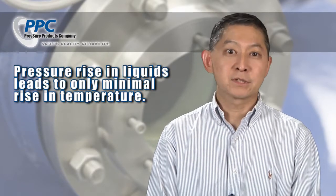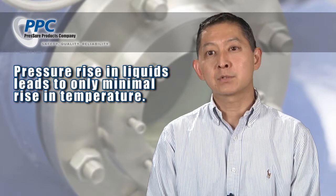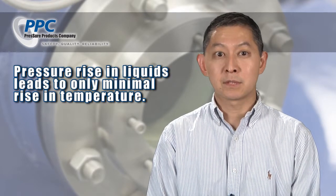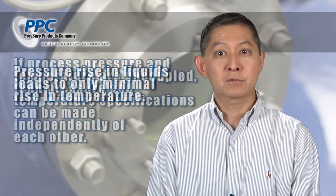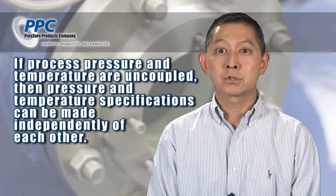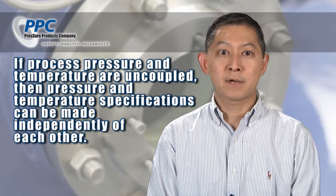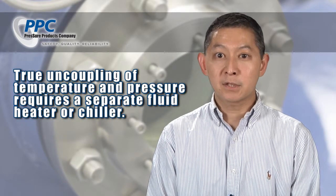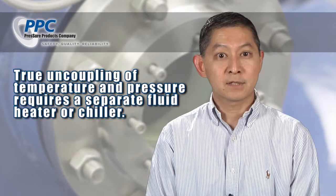Now, that total absence of safety margin on the temperature scale is generally okay for liquid processes. Pressurizing liquids to 150 psi is hardly going to raise their temperature. In fact, pressurizing even to 600 psi will raise the temperature very modestly. Also, if the fluid pressure and temperature are truly decoupled, not having a temperature margin of safety would be okay. So if you have a process involving very high temperature liquids, like motor oil, and you pressurize that to 150 psi and heat to 450 Fahrenheit in separate steps, a commercially available side window with those ratings will be fine. In fact, this is how side windows are generally tested.